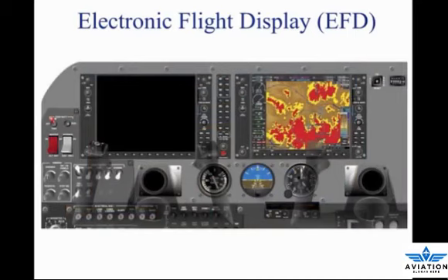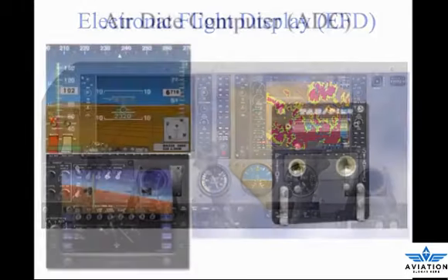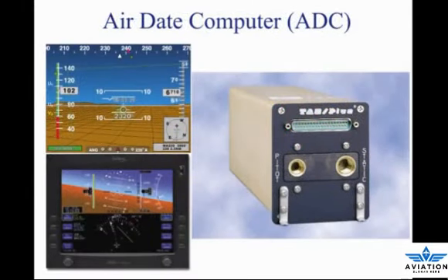The sixth instrument, normally associated with the six-pack package, is the tachometer. This is the only instrument that is not located on the PFD. The tachometer is normally located on the multifunction display, MFD. In the event of a display screen failure, it is displayed on the remaining screen with the PFD flight instrumentation. Individual panel displays are able to be configured for a variety of aircraft simply by installing different software packages.